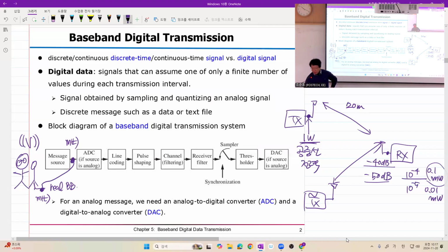noise and interference are necessary to consider because this signal is very small, so you have to amplify using a so-called low noise amplifier. However, a low noise amplifier, as the name says, has little noise, but huge amplification. But there is noise. That's the key. And this noise is actually all about the electrons in our circuit or metallic material passing through the grid of the material, but it collides with the grid so that we have ohmic current flow phenomena.